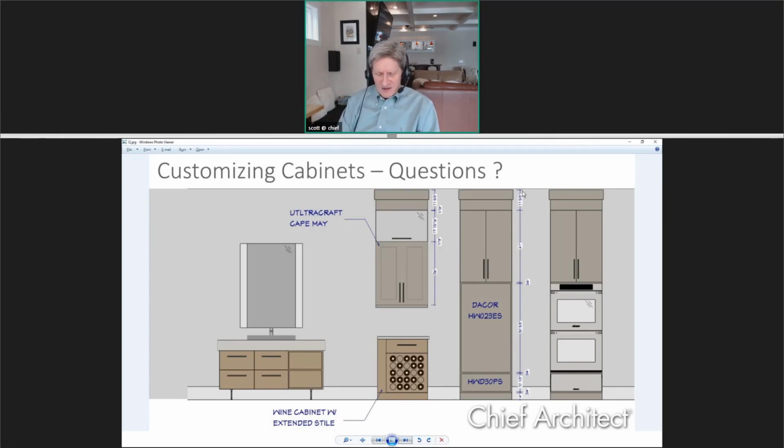Yeah, so apron sinks are really designed to sit on top of the cabinet. So they don't insert into a cabinet as an undermount might. And there's a couple ways depending on what you're doing with those sinks. One, if they don't have any stiles on the sides, if they're taking up the entire cabinet, a lot of times I'll just set the cabinet lower, say pick a number like 24 inches, and then I'll just set the apron on right on top of that, position it in the plan view.